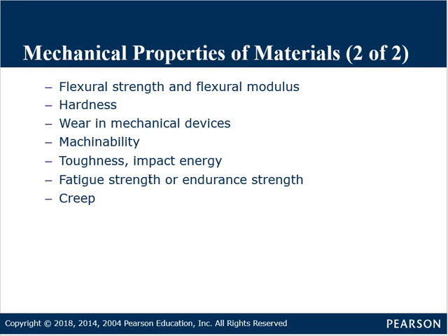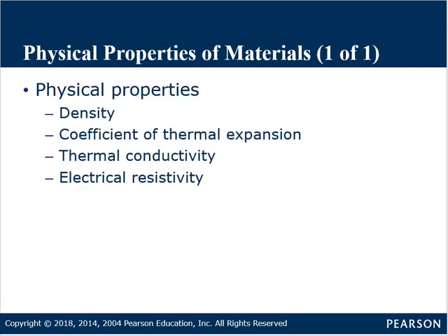So if you have a load, even though it's below the yield strength, it can cause a part to fail if that load is applied over and over and over. So anytime I want you to think of endurance and fatigue, think of repeated loading over and over. That's endurance and fatigue.